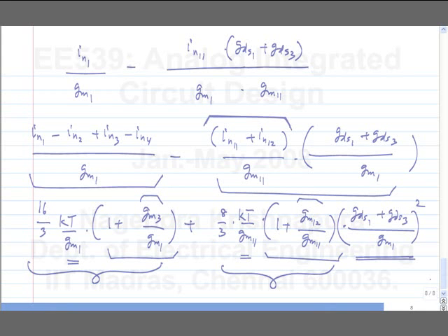So the similar thing holds for mismatch. Now the only other thing that's left to do, and which involves some reasoning, is the slew rate. So we'll discuss that on Friday. Think about what the slew rate of this op-amp is going to be. I mean, what limits the slew rate? Why would it be limited? Any questions?